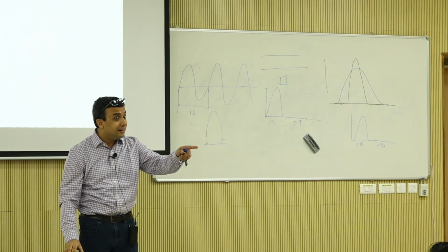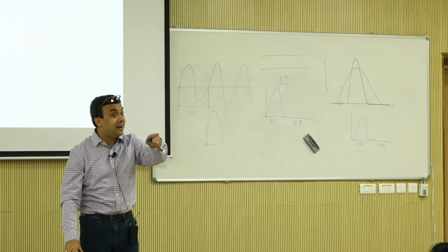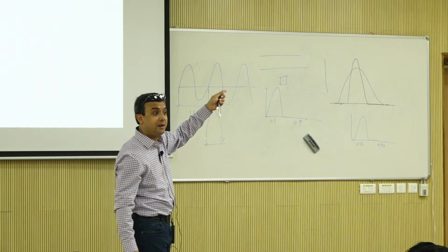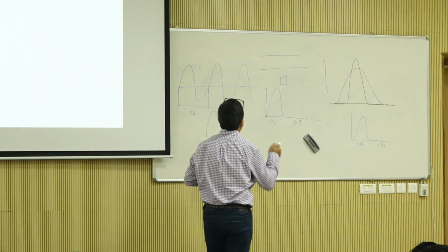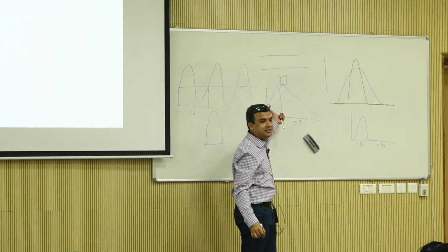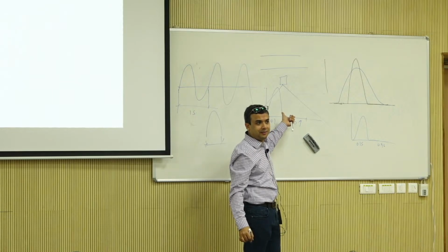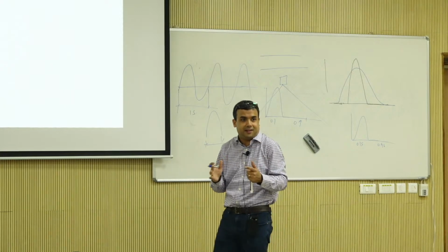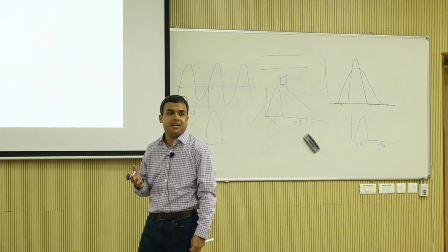Upper layer stiffness, not the same layer stiffness, the upper layer stiffness. Why? Because that determines at what angle this load is going to get dissipated, right? Sometimes people say it's 45 degrees or something like that. That also can change, right?